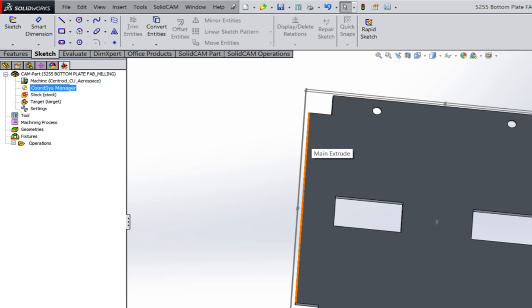No, I'm hovering the drill bit just barely over the top of the part, like that. Why is that no bueno? You're just eyeballing it. So you're introducing error on your perception of your sight. Okay? What should I use to find this edge? An edge finder. Wow. So you would edge find this edge. You've been shown how to do that, right? And you would edge find this edge, set this as X, set that as Y.